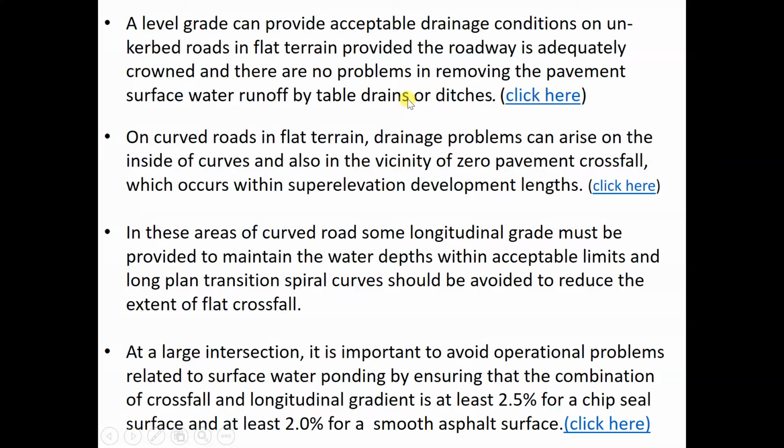The water can flow down the slope, but not the whole slope. They usually have steps. The water can only fall, let's say, 5 meters. You cannot let the water run down a slope of about 20 meters, because it will create a lot of erosion.